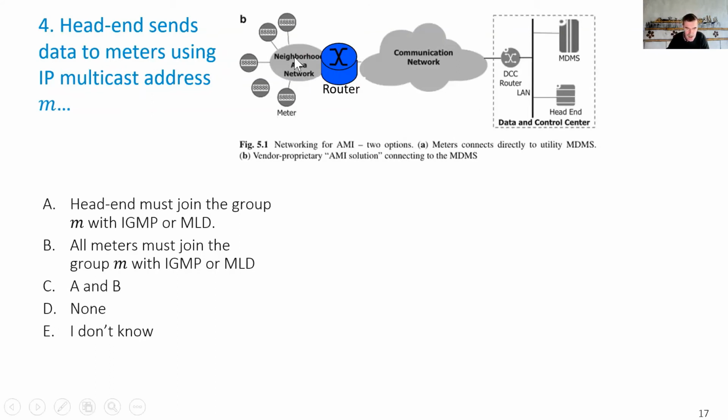Here's an example where I have smart meters. Smart meters communicate typically over the power lines, using communication that is a mixture of wireless and wired. It is wired in the sense that the communication signal goes over the power lines, but it's wireless in the sense that it also radiates in free space. For example, if you have two electrical cables that are together but insulated, not in the same phase, then the signal can jump from one cable to the other. So that's power line communication. That is very efficient whenever you find it too complicated to lay cable.